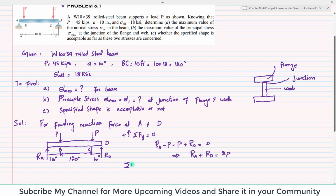Now we will apply the second condition of equilibrium, that the sum of all moments about any point is zero. So we will take point B. Sum of all moments about point B is equal to 0. At point B, this reaction force is producing moment in clockwise direction. So it will be Ra into 10, and that will be negative because it is clockwise. Similarly, the moment due to this load at point B is minus P into perpendicular distance 120 inch, again clockwise, so negative.